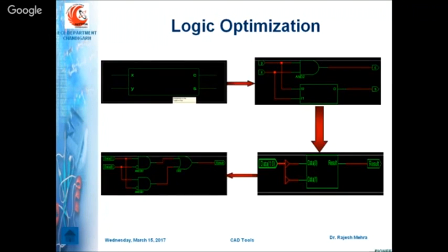So once this logic optimization is done, then your RTL will be converted into a set of gates, and you will go inside the circuit, you can say, and you will get one final minimized circuit, as I told you yesterday, with a minimum number of resources along with their netlist connection between different components, so that you can reduce the number of resources in your design. You can enhance the speed, and you can reduce the power consumption. So after logic optimization, you perform all these optimizations.